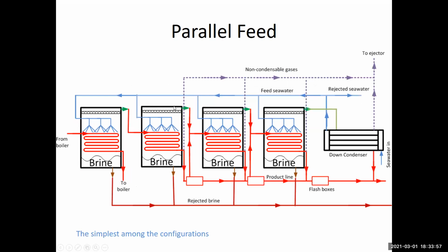So we have got a benefit here by having to use steam from outside to heat only 1/4 of the feed seawater, or maybe 1/6 if it's a 6-effect system, or 1/8 if it's an 8-effect system. But in each effect, the vapor that I'm going to form will first be utilized to preheat the feed and then evaporate it, preheat the feed and evaporate it, and so on. So at the end, which one is better? I cannot answer it now. We have to do analysis to see which one is better.